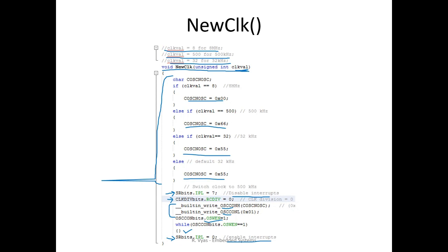A lot of embedded coding is often known as energy-aware embedded coding, because of the constant need to throttle clocks to save battery power. And that's what's happening in your phone as well. Your clock is never steady. While your phone's in your pocket while you're listening to this lecture, hopefully, you're running it at a very slow clock speed. But the minute you lift it and turn the screen on, the clock ramps up. So even behind the scenes, there's a lot of clock switching going on all the time. Questions?